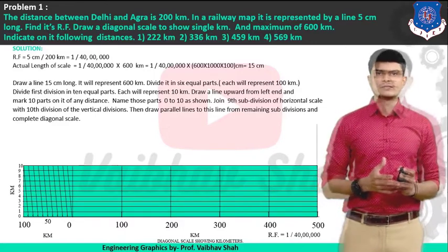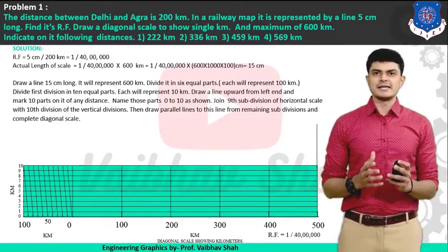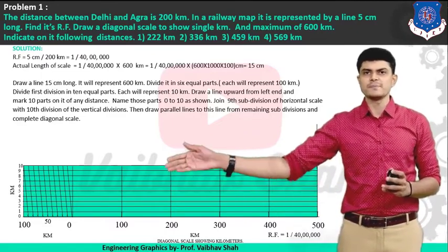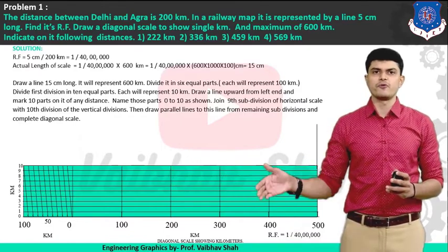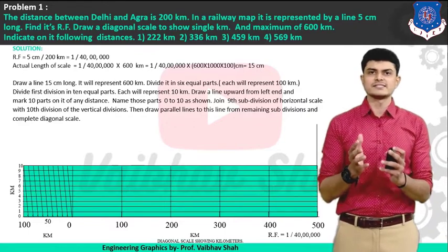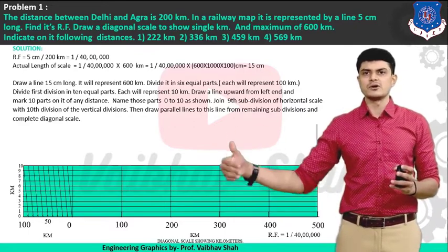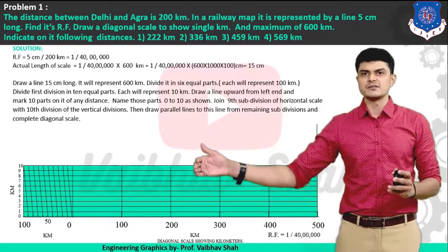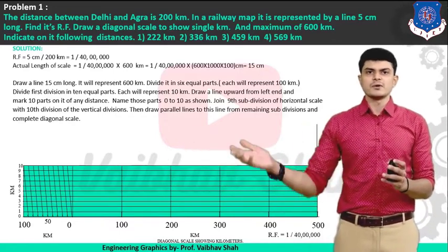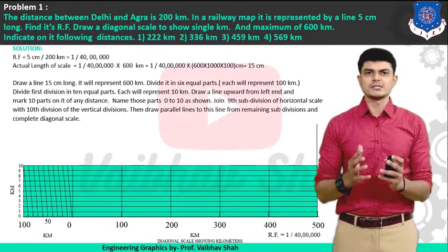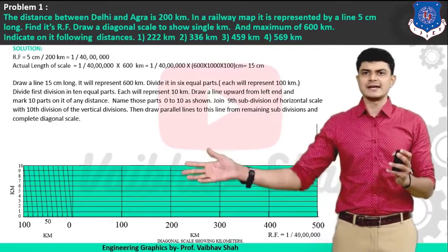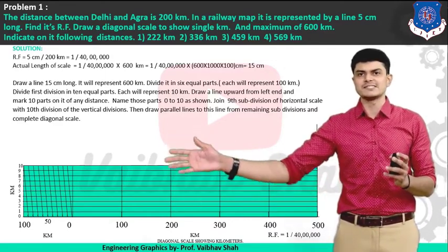Let us start with the primary scale. As we start from 0 towards the right hand side of the main scale, let us go 0, 100, 200, 300, 400 and 500. Let us draw a vertical line. Now next is your 60. Let us draw from 0 towards your left hand side for 6 divisions: 1, 2, 3, 4, 5, 6. So you will have your division just on the left hand side of your 50s, which must be showing you 60 distance on your secondary scale. And you can see that there is one inclined line passing from your 60 division.